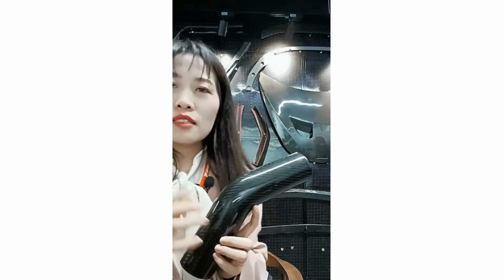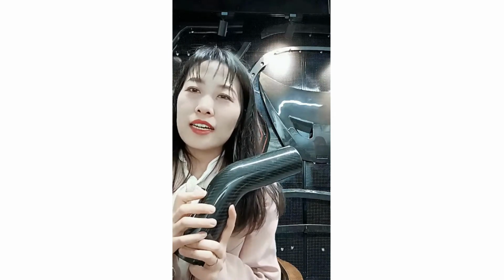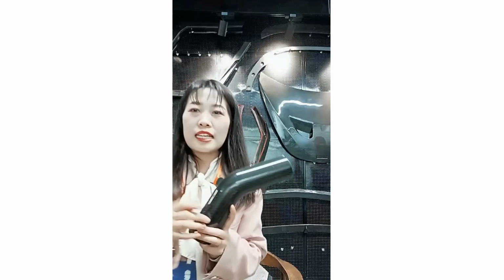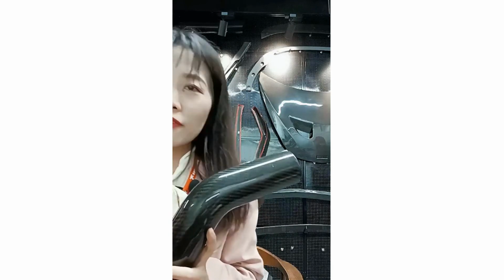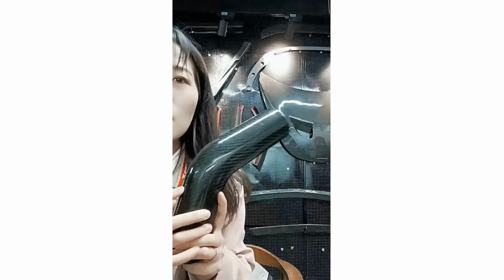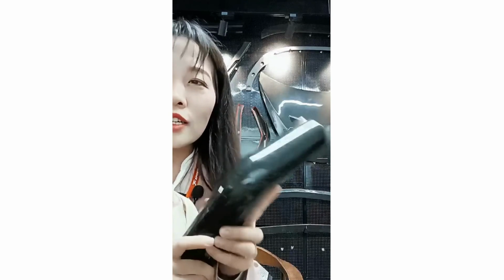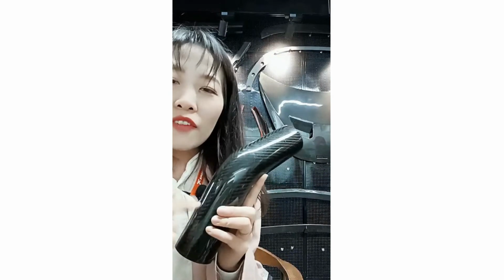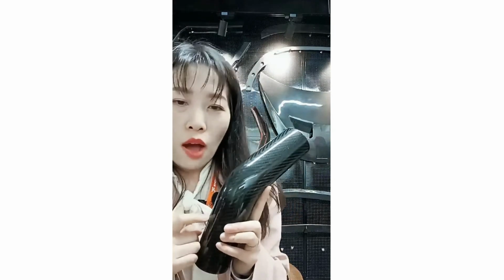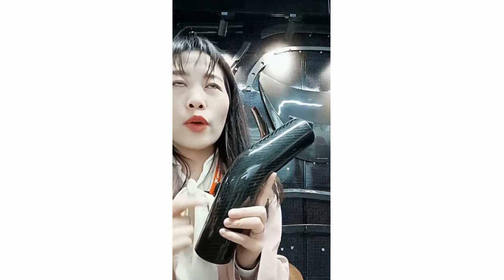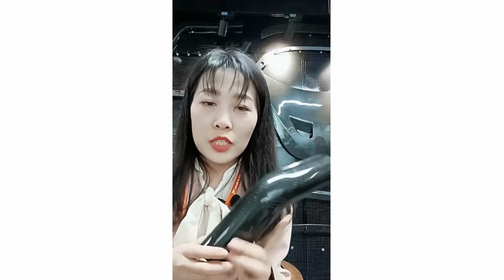The strength of a component is difficult to compare like for like with a steel part, but in terms of stiffness, the dry carbon fiber parts are comparable in stiffness to the original. But it also comes with super light weight. If the original bonnet is around 20 kilograms, we can help you reduce the weight by half if you make it in dry carbon fiber material.